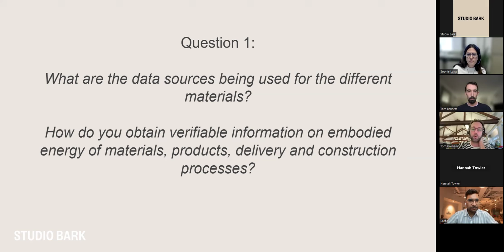Everyone needs to try and work towards getting an EPD for a product. Ideally you want something that's been third-party verified and is in date, so you need to check the expiry date on that EPD to make sure it's from a recent point in time. That tells you the carbon intensity of that material going into your building. But that's the ideal situation.